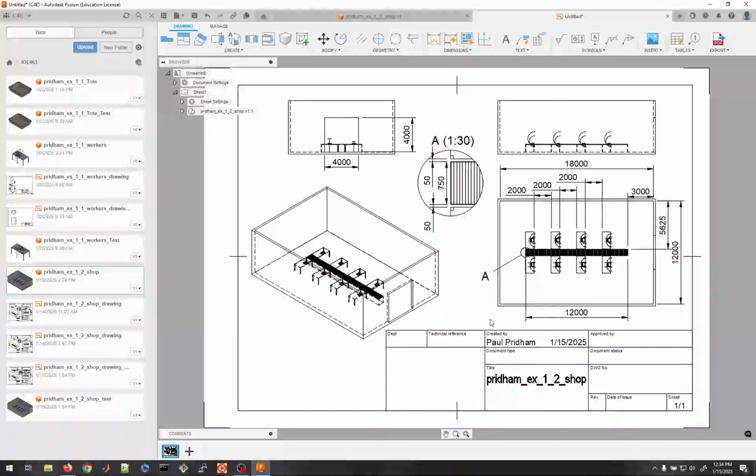This is nice just to prevent people from not being able to see exactly what information is important because they have 200 different dimensions on a single sheet and it's impossible to read. So you have to use your judgment in terms of how much to provide on a single sheet, what level of detail you want to go into, and how to group them.